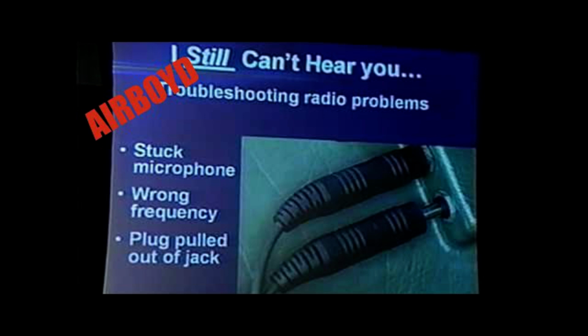2. When an ARTCC radio frequency failure occurs after two-way communications have been established, the pilot should attempt to re-establish contact with the center on any other known ARTCC frequency, preferably that of the next responsible sector when practicable, and ask for instructions. However, when the next normal frequency change along the route is known to involve another ATC facility, the pilot should contact that facility, if feasible, for instructions. If communications cannot be re-established by either method, the pilot is expected to request communication instructions from the FSS appropriate to the route of flight.